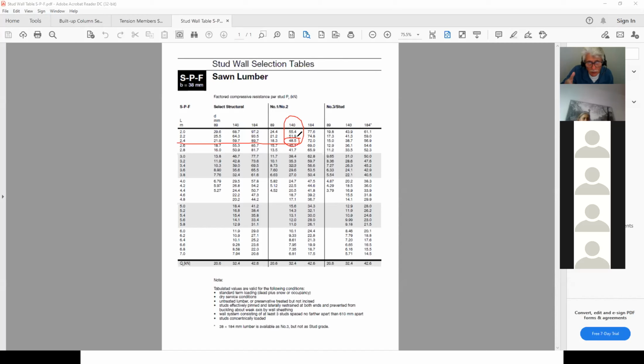So that's one thing: if you understand how these tables work, it can greatly simplify your life. If you don't realize you can use the tables, then you'd have to use the whole PR formula with phi, C, A, K_ZC, K_C, blah, blah, blah, and find your PR value through that. But here, because you've answered yes to all the questions in the checklist, we can use the table. So I get my PR value in kilonewtons right away.